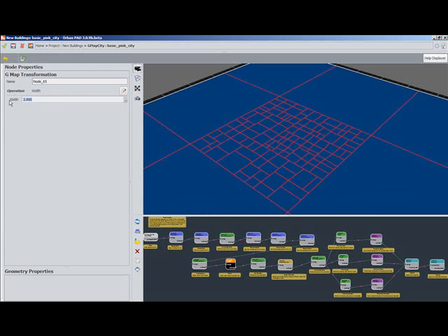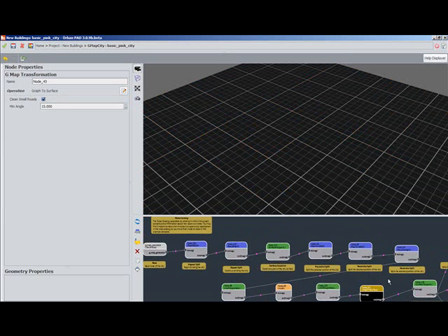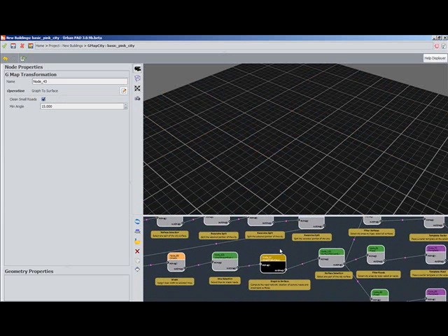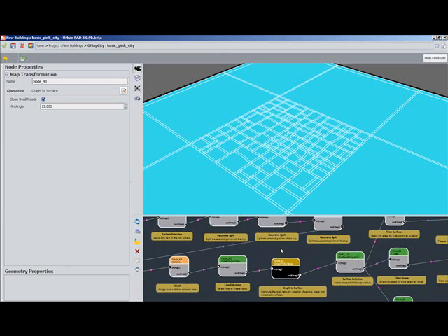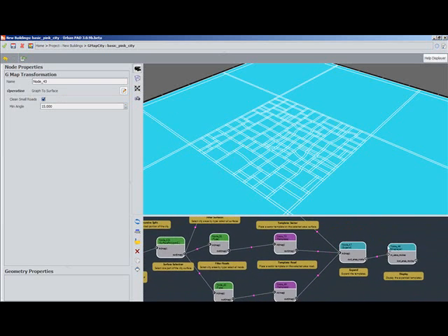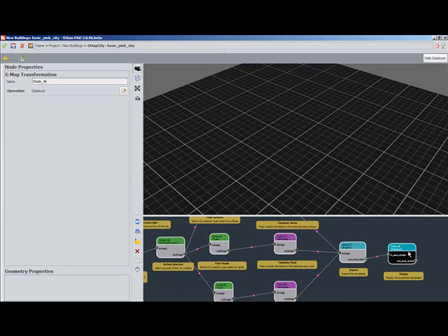Okay, so I've gone to the width node. I'm going to change the width of my roads. I'm going to roughly double them. I'm going to click on my graph to surface node, which is the node that is used when I want to draw my city before I add my templates and display it. And you can see an update of the information with this new road width on screen. Going to click the display node to display the new city with the new roads.